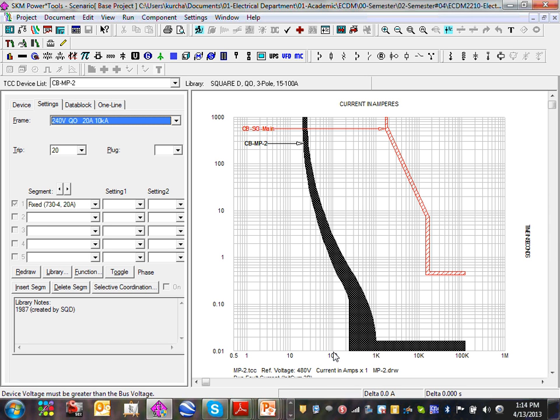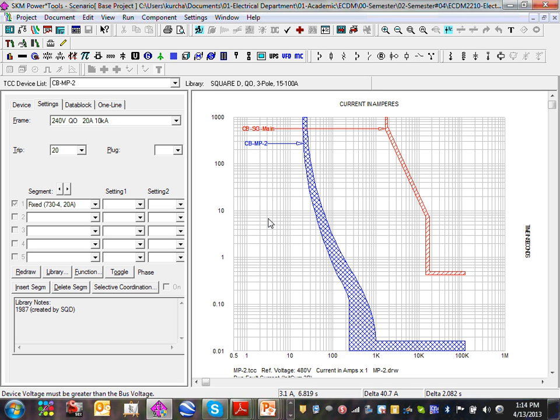But if you put 100 amp through the 20 amp circuit breaker, look how long it will take to open. Can you guys see that? Cool. 100, 100, 100, up to close to what? 1 second to open. That's what they call non-adjustable. Do you see anything to adjust here? That's what you call a dumber than a rock circuit breaker that you can buy. Nothing. What you see is what you get. Any comments, guys? Any questions? Inverse type, you can see the curve is going this way. The higher the amp, the faster it trips.